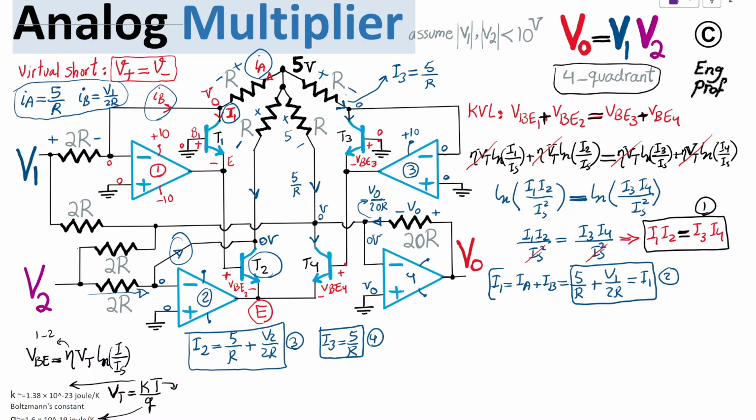Okay, great. So the only thing remaining is what is coming this way or going that way. That is again not difficult because here is 0 volt, and you can see that across this 2R we have a V1. So basically this current as a result is just V1 divided by 2R.